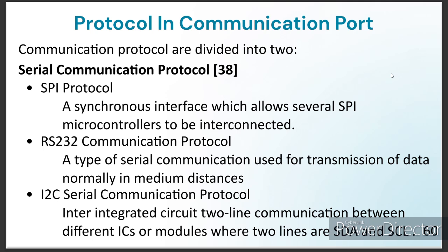I2C combines the best characteristics of both SPI and UARTs. I2C allows you to connect multiple slaves to a single master and have multiple masters control single or multiple slaves. This is extremely useful when more than one microcontroller is logging data to a single memory card or displaying text to a single LCD. I2C transfers data in the form of messages.